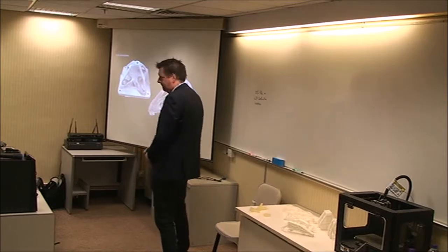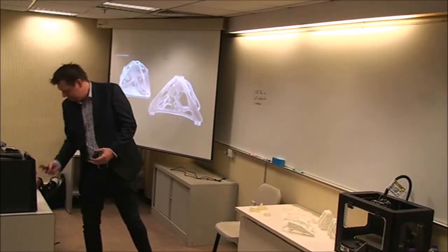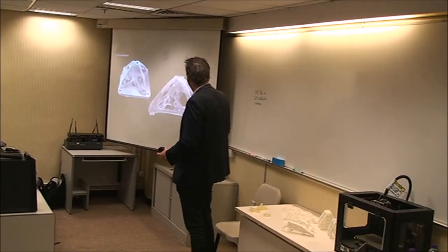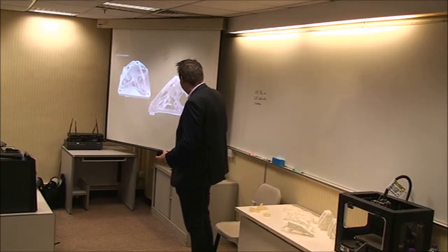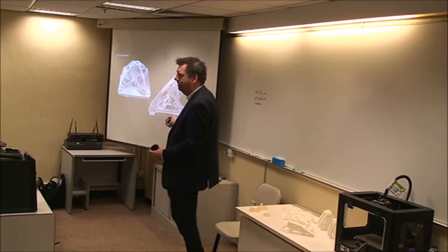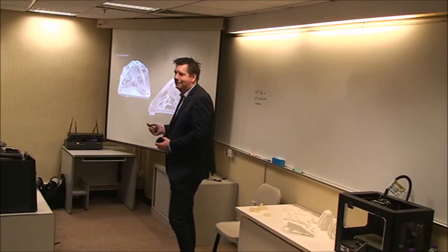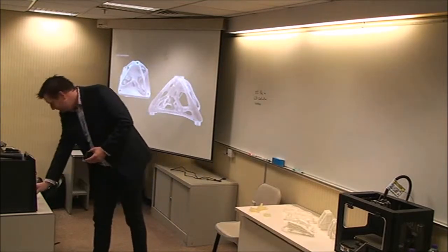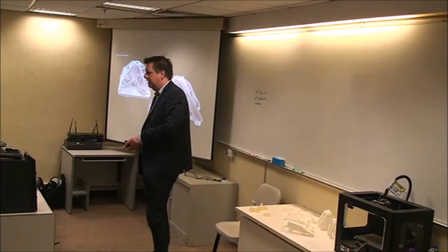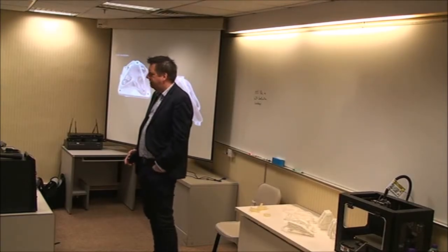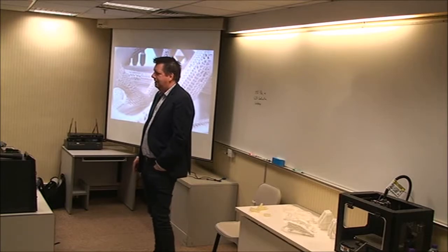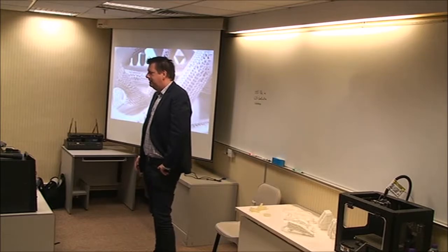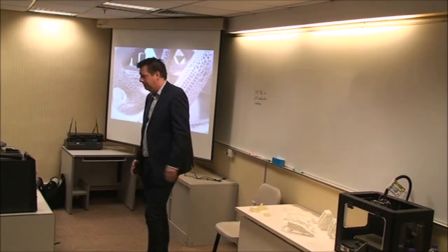So you can see, is the pointer on this one? Yep. So you can see the solid areas up here and up here. But it's these transition zones that I actually don't like, and most people would prefer a cleaner lattice to solid transition. So for the parameters we set, that was the optimum result, and you get these very nice looking lattice structures out. You can see there's a slight taper on a lot of the beams there. So for the lattice that's there, it's been optimized.